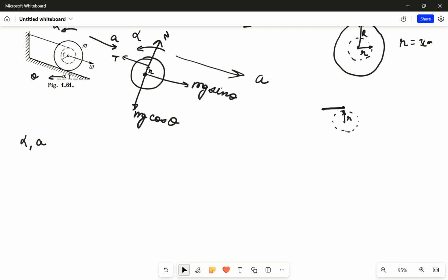of the string and the inner radius, right? Let's name them A and B. So as you can see, as the string unwinds itself, the velocity of A and B would be the same, as these points are in touch with each other, so their velocity would be the same, right? So what we can say from this is, let's say at that instant when these two points were in contact, its angular velocity was omega and its linear velocity was v.